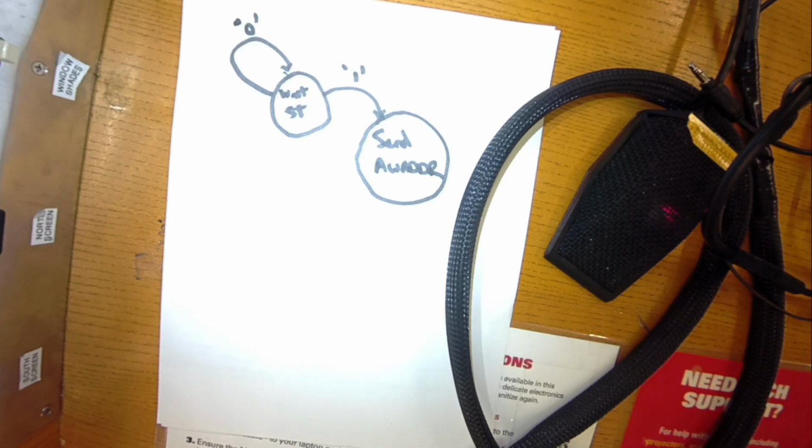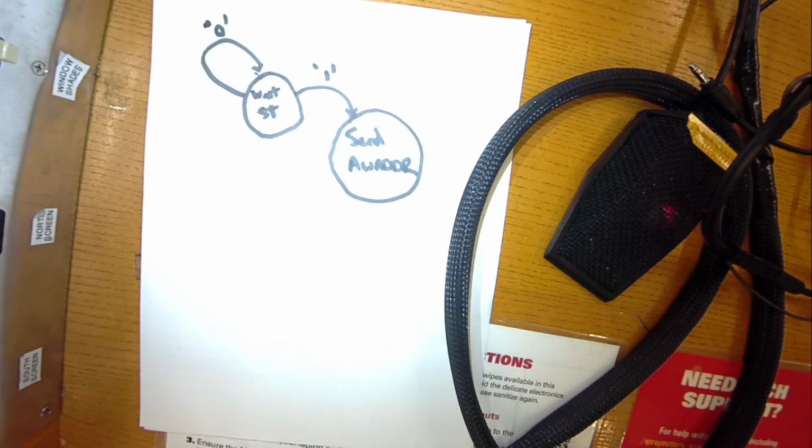And that would be a process that's just doing that. I'm going from state A to state B to state C. That's a nice thing to separate out because you can really reason about it just looking at the code. And your diagram should match the code pretty much on a 1-to-1 correlation there, right? That rising edge of clock, I have a register holding the state information, then I go from this state to that state to this state based on some combination of input signals that we have here.